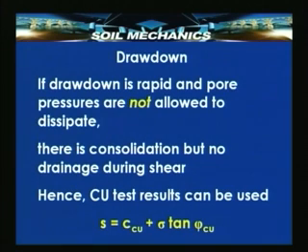They are simply equal to the additional axial load applied during the undrained stage, the second stage of loading. Since the pore pressures are known, although we get the total stresses and shear strength parameters corresponding to the total stresses, we can always easily calculate the effective stress and the effective stress parameters and use them. And in fact, often this test is preferred to the simple consolidated undrained test.